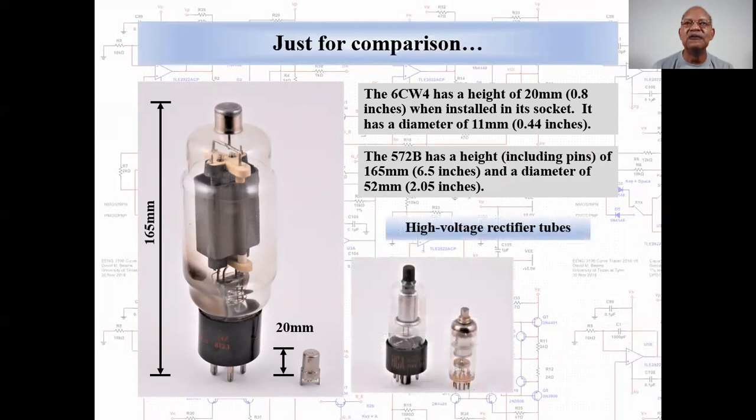These tubes are meant for very high voltage applications. These are both diodes, and the use of a cap is not required because of a lack of pins. The cap is meant to give the greatest possible separation between the plate and cathode terminals, since these tubes were meant to operate at up to 25 kilovolts. These tubes were often operated in shielded cages to stop any soft X-rays which they could produce.